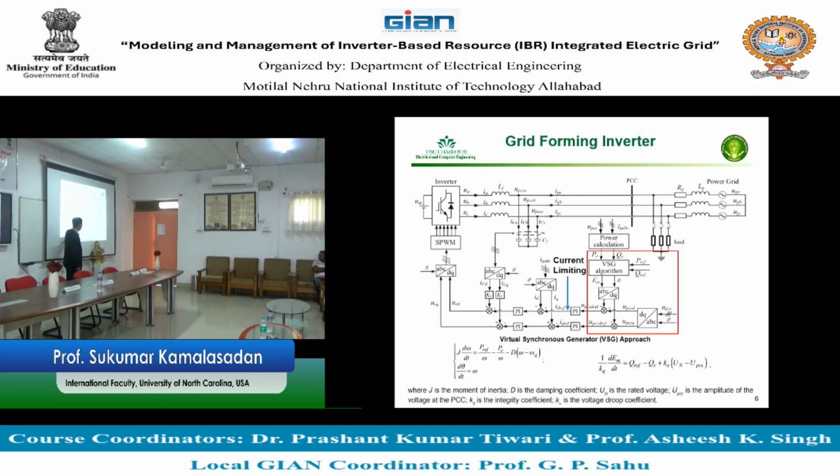That power you know. What about this? It's a number. What about this? Well, that you can tap from the delta. This is a number, right? So these two numbers you can place there and generate this equation right here, and then generate this angle and the voltage. This is what we know as a virtual synchronous generator. One form of virtual synchronous generator is called the swing equation form of virtual synchronous generator. So only the swing equation you are considering, only the mechanical part.